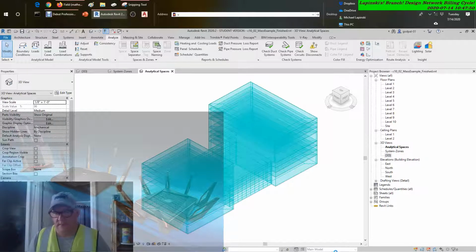In any event, the energy analytical model may be out of date, and again, it could be updated with all those particular bells and whistles. Now, when you run the initial analysis, you get a potential warning message. This message states that there is some variation in the levels of complexity with the model. If you're performing the analysis on the model that was provided with this chapter content, there are some building elements that are significantly more refined than others, largely based on the phase of design this model is currently in. The dialog box simply calls your attention to the variety of complexity. If you're unaware of the variation, this is an opportunity to investigate before the analysis run. For this exercise, choose OK to continue now.